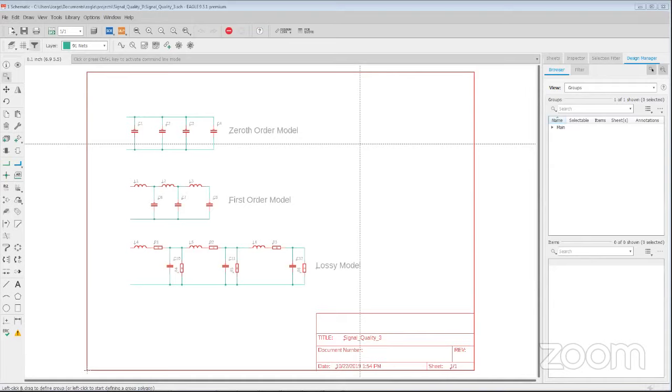Let's say you have a pair, and you connect a battery to it and the other end's open. As soon as you put a meter to it, it's going to read as an open circuit. But if you were able to freeze time and go right after the instant in which you've hooked up the battery to the end of the wire, you'd actually see this wave flowing. At each step of the way, you have this wave of an electromagnetic field moving along the length of the transmission line, charging up these capacitors along the way.